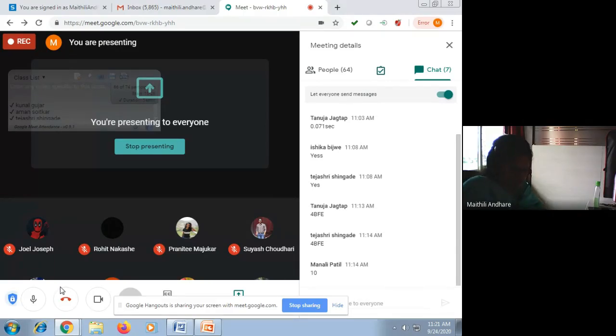So for the timer, we started with the timer modes, then the registers: TMOD register, TCON register, and then the TH and TL registers, their organization, the theory part. Then we saw the hardware diagram: how the timer frequency is divided by 12, then the GATE bit, then the INT bit, then the TR bit, the timer's different modes, how TL and TH operate in the different modes, and what the size of the timer is in different modes. This all theoretical part we have completed.